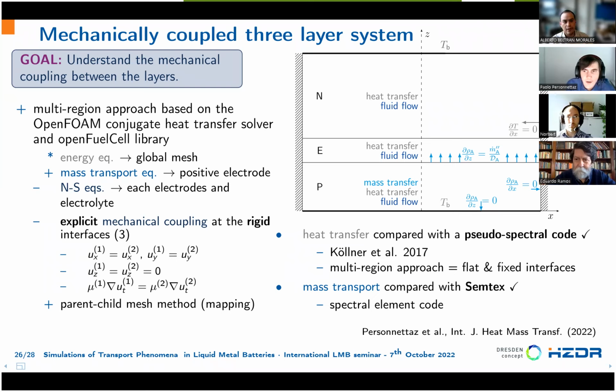I have one question. It has been reported in the literature that at the interfaces, there is the generation of an electrovortex flow due to this bending of the current distribution of the electrical potential. When you talk about this non-uniform current distribution in the simulations and for the 3D layer system, did you perform 3D simulation, or will it be important to consider the effect of a rotationary flow near the interfaces?